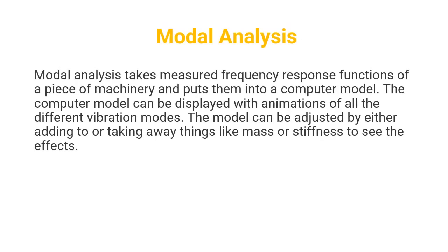Next, we have modal analysis. Modal analysis takes the measured frequency response function of a piece of machinery and puts it into some sort of computer model. The computer model can be displayed with animation of all the different vibration modes. The model can be adjusted by either adding or taking away things like mass or stiffness to see the effects on it.